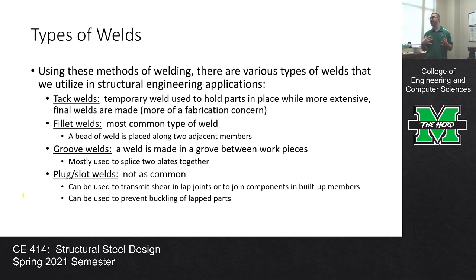First off, I think I would be remiss if I didn't discuss the tack weld, because I think every single welding operation involves a tack weld. Now, to be clear, tack welds are not something that structural engineers design, because their purpose is not to resist load. Their purpose is not to support a structure. Their purpose is only for fabrication.